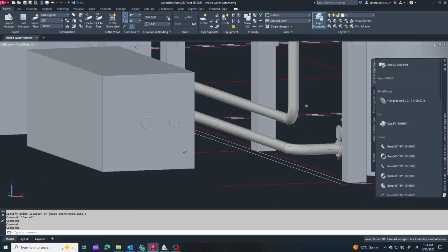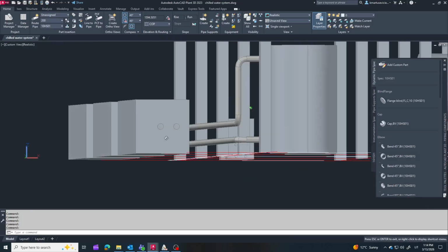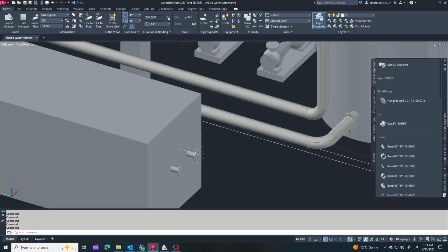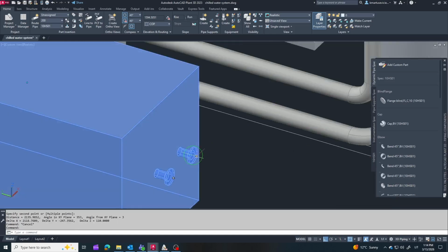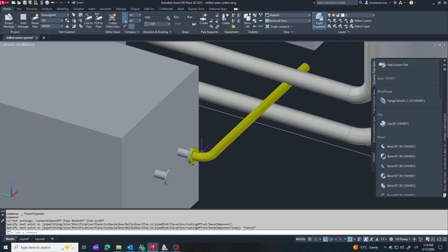A chiller removes heat from the water using a refrigeration cycle. Inside the chiller, refrigerant evaporates in the evaporator, absorbing heat from the chilled water. This cools the water that circulates through the system.